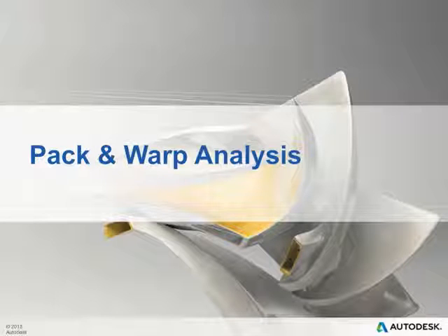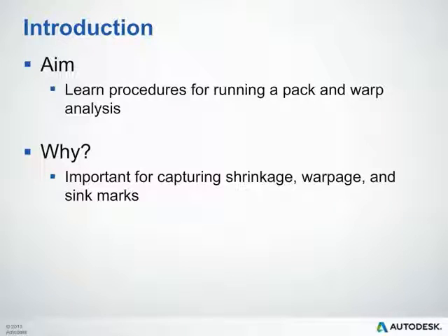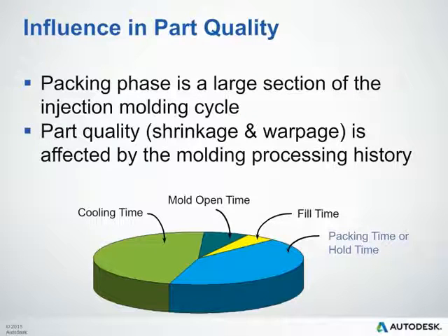This module will cover the pack and warp analysis. The goal of this module will be to learn the procedures for running a pack and warp analysis. Why do this? It's important to capture the shrinkage, warpage, as well as the sink marks in your part. So, the influence in part quality.